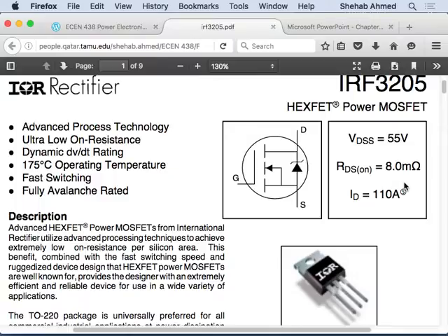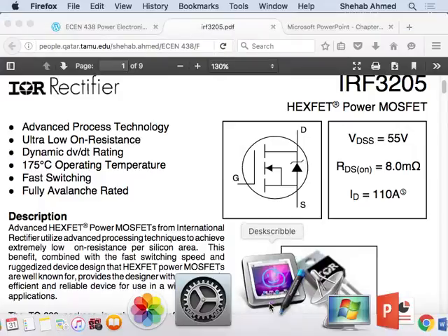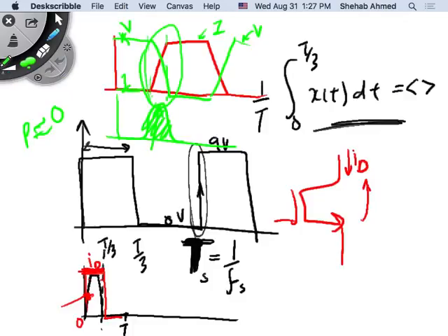So does that mean if we increase the frequency of the switching, we have more dissipation? Of course, you have more switching loss. There are two types of losses. When the device is on, remember we said, this is the device on, right? We said that there's always going to be, here the voltage theoretically went down to 0.